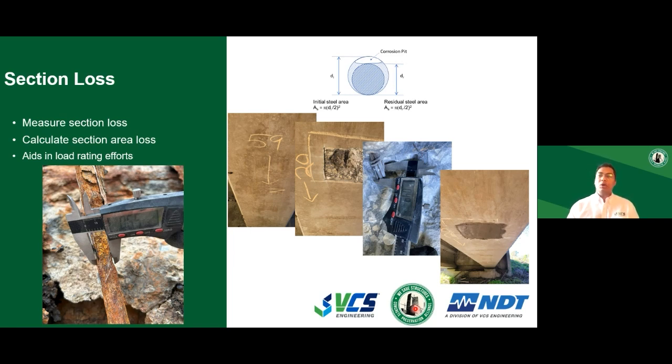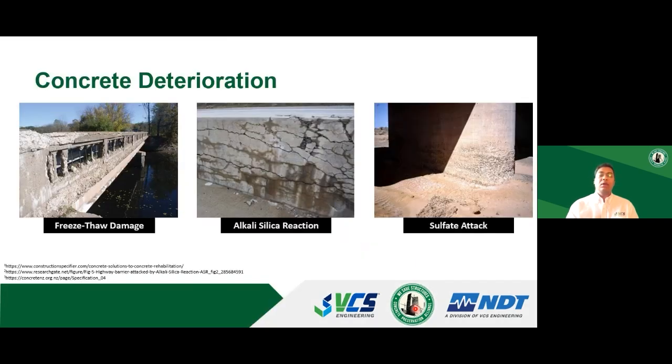Now, this was all about chlorides and carbonation and rust resulting in cracking of the concrete. So the rusting came first, and then the concrete cracked. But it can happen the other way around as well. If your concrete is exposed to freeze thaw effects, or if the aggregate is susceptible to alkali silica reaction or sulfate attack, then you can have concrete cracking first.